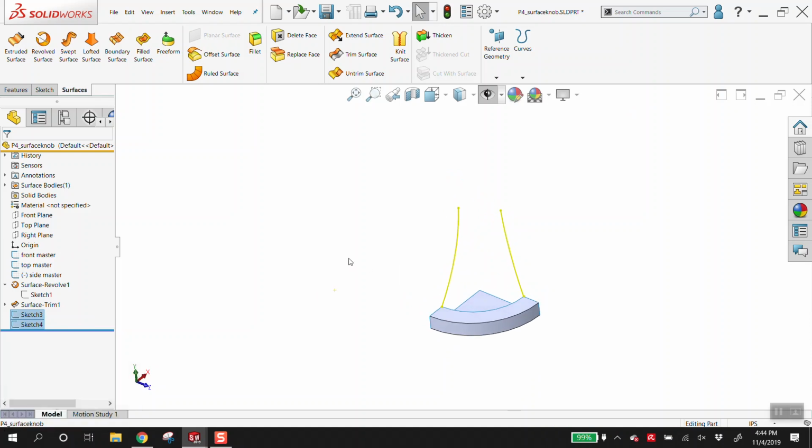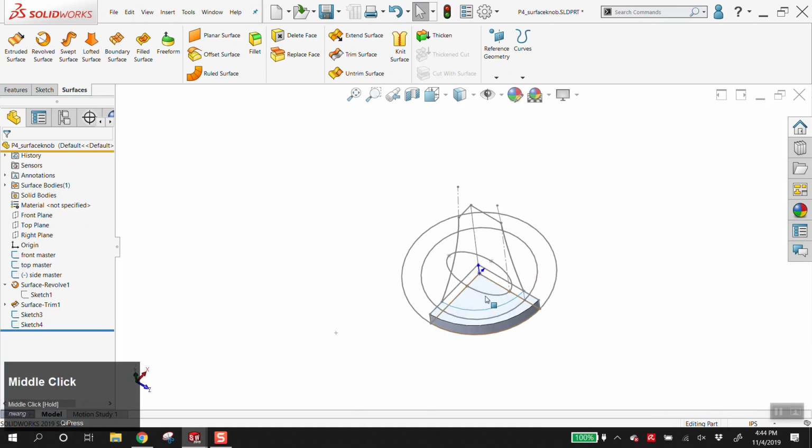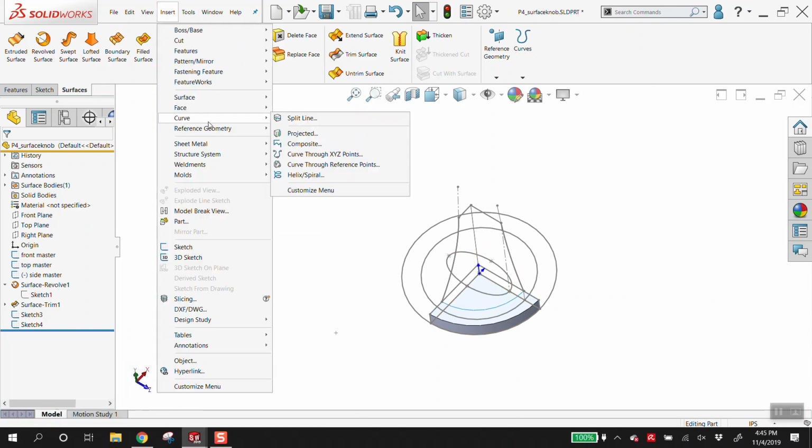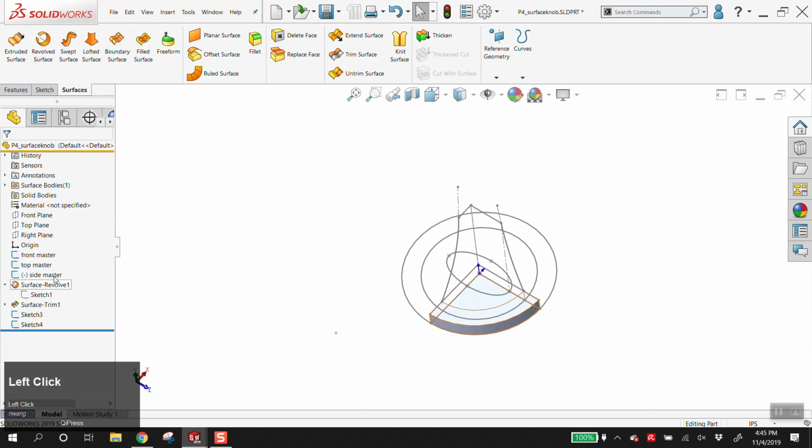If I look at what this has us do, it goes right into a loft, which is totally okay. You'll notice that there's this in the master. You could, if you wanted, this is not in the demo, but just for your reference, if you're trying to control that loft a little bit more, you could, you know what, sorry, let me back up. I'll show you what the demo talks about, and then I'll show you a slightly more controlled way to loft it. So the demo then has you take these two sketches and loft them together.